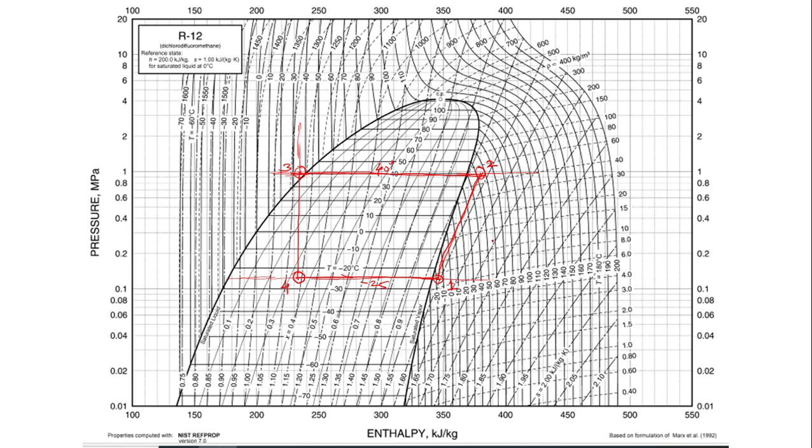You just follow the straight line from point number 2, wherever it is coming down. Now I don't have the scale over here, I'm just drawing roughly. It is between 350 and 400, so around 375. So enthalpy is 375 at point number 2.